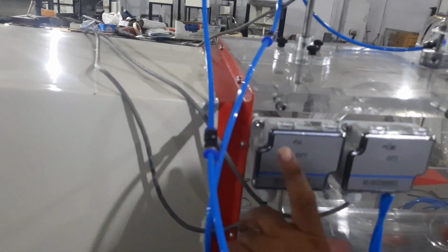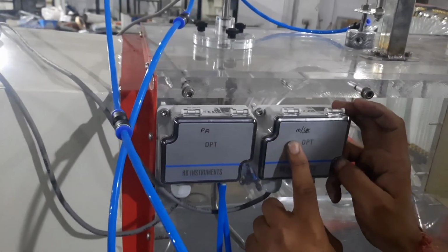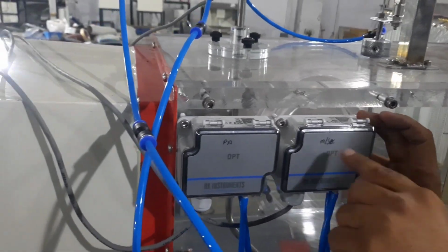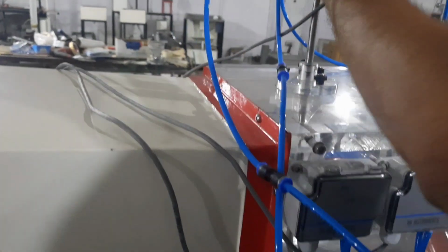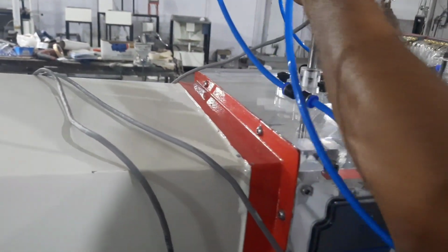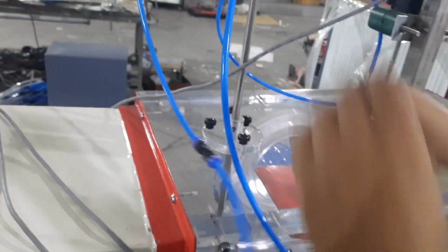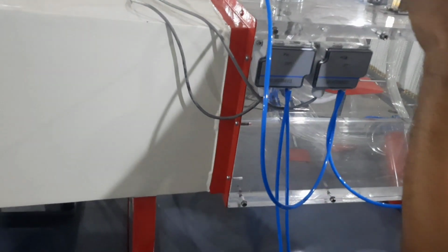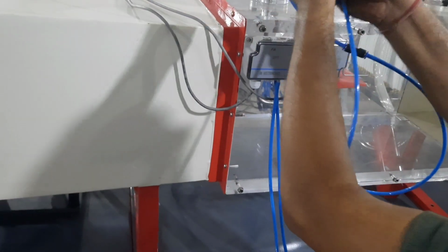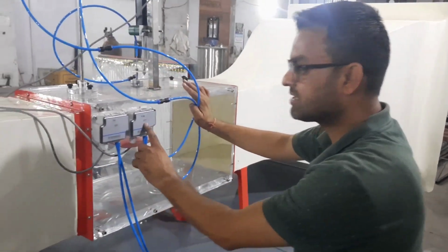One will show you the readings in pascals of differential pressure, and another is calibrated to show you the velocity in meters per second. Suppose you want to know the velocity inside the test section, you have to adjust it with the help of this around the test section, and then connect the two pipes for the total and static head. At the side of the test section, you will see the two pressure transmitters.